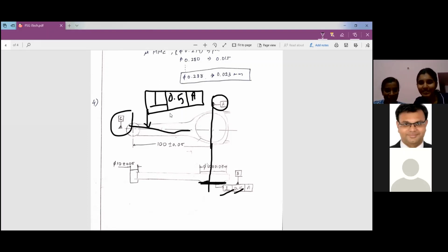What about the flatness? Where does it become flatness? It is this surface, but I don't think it will be perfectly flat, sir. So we didn't mention it. How much can the flatness value be approximately? 0.01. Yeah, okay. No need actually, I'm just asking. And what about parallelism? Sir, there will also be parallelism of these two axes, and there will be circularity for these two circles, sir. We actually didn't have time for writing all this.